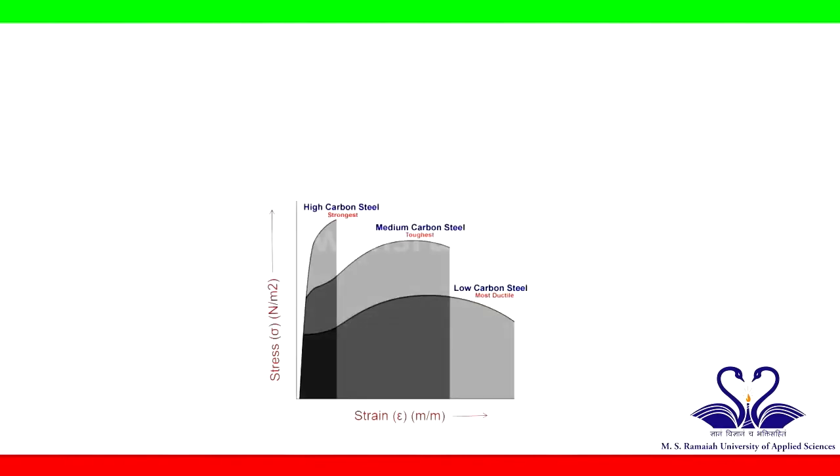We can see the stress-strain diagram of high carbon steel, medium carbon steel and low carbon steel. It can be clearly observed from the figure that as the percentage of carbon increases, the strength of steel increases, whereas ductility and toughness decreases. High carbon steel has the highest strength and low carbon steel is more ductile in nature.